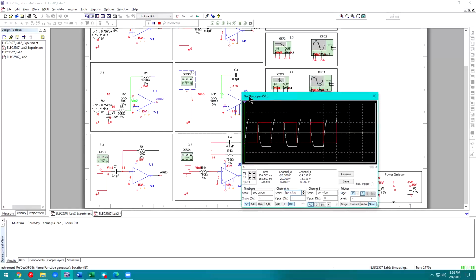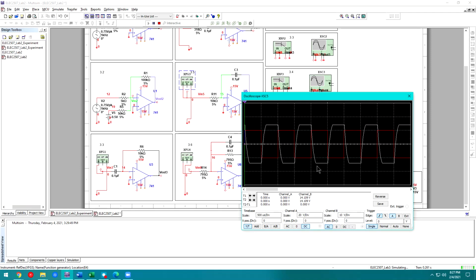But it's going to act more like a sawtooth, as we saw in the previous section, right? But what are these little ramping and deramping stages? That's actually the capacitor's charging and discharging cycles, right? So you see that small little curve. You talked about that in 2501, and you can calculate that based off the RC constant.